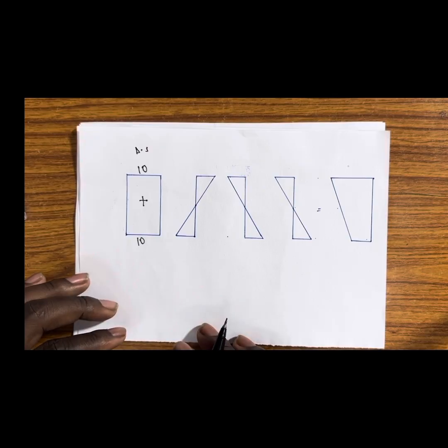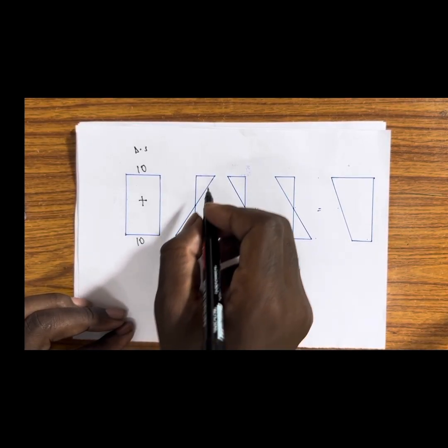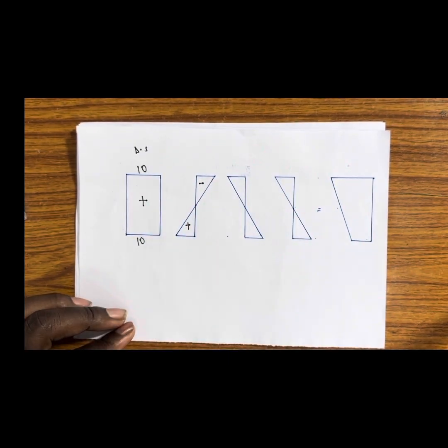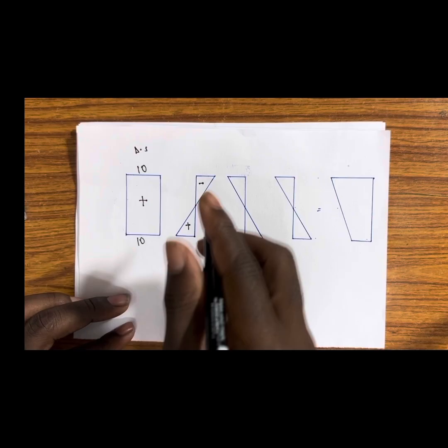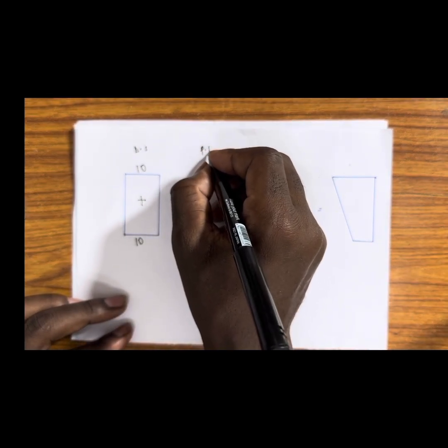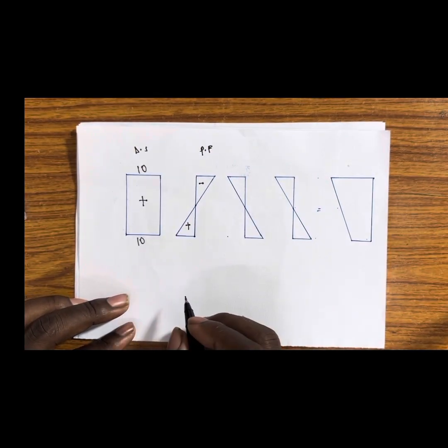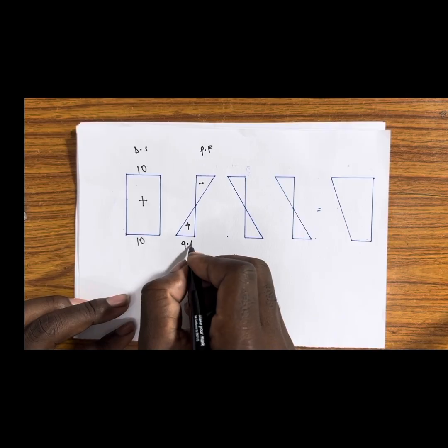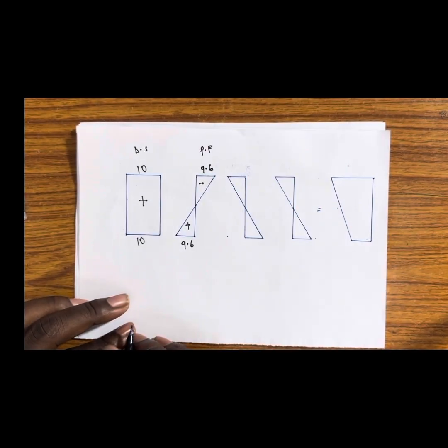The second one that we have, down is positive, up is negative, and this is a bending stress due to pre-stressing force P. So the second one is due to pre-stressing force, and we calculated that, we found that it is coming to 9.6 top and bottom.